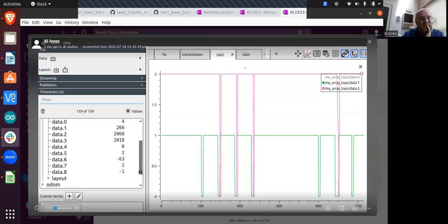So my hypothesis, but it is just that, is either interference around the house or something else at 915 megahertz, or I'm just trying to do too much with this ESP32 board, driving the OLED, running LORA, and the other computing load on there.